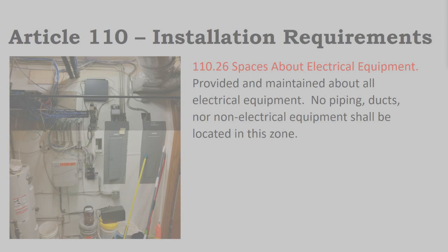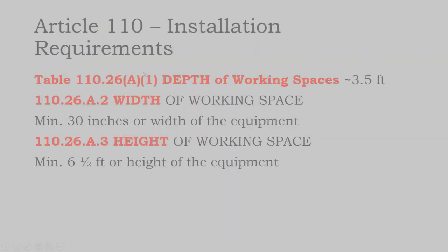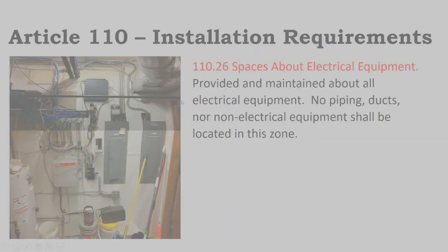Where the code violation would be is that it's not installed in a neat manner. And then there are other code violations too. That duct work above the service panel needs to be of a certain height. All of that can be found within the National Electric Code, including spacing from your plumbing. And you see here that hot water heater is likely too close to that fiber optic equipment.